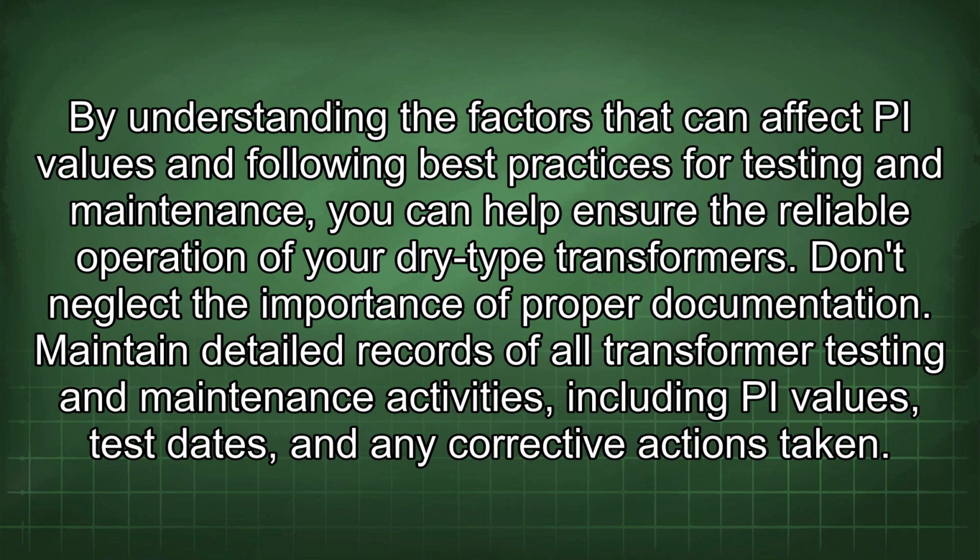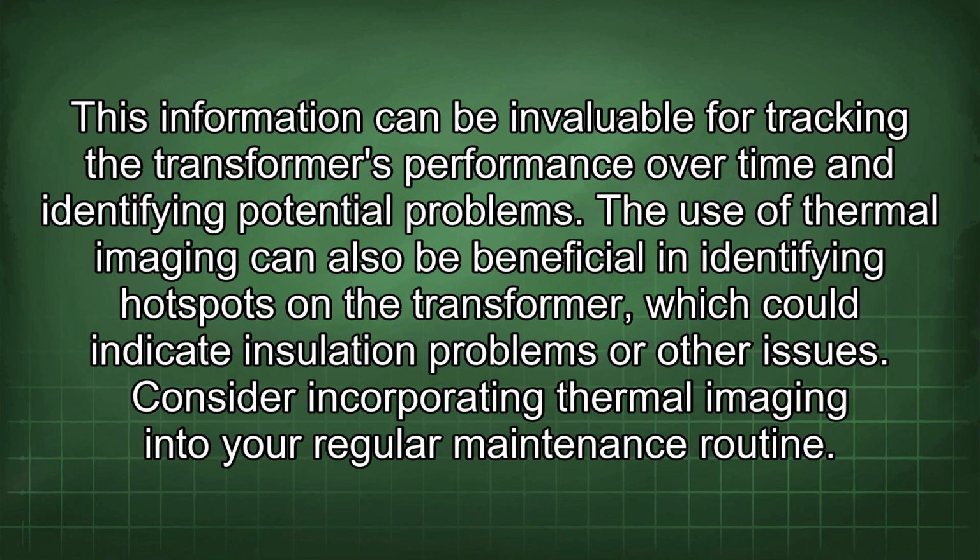Don't neglect the importance of proper documentation. Maintain detailed records of all transformer testing and maintenance activities, including PI values, test dates, and any corrective actions taken. This information can be invaluable for tracking the transformer's performance over time and identifying potential problems.